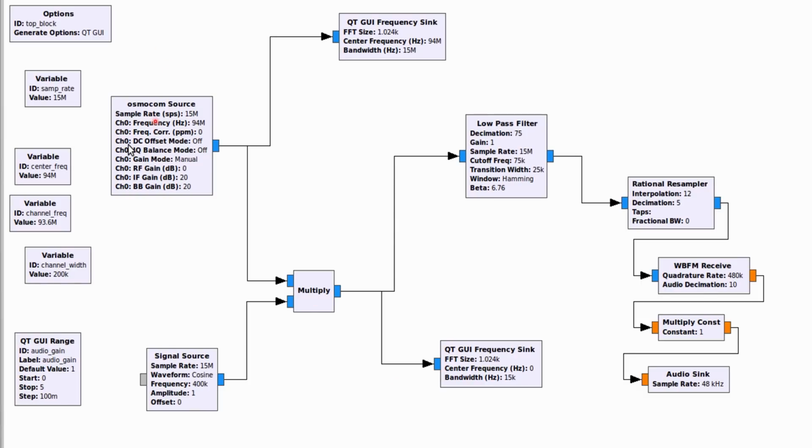It takes the IQ signal of the SDR receiver, demodulates it and sends it to the speaker. We easily can change the frequency to 145.525 MHz and the modulation from wideband FM to narrowband FM. Now we can listen to amateur radio. The same applies, of course, also for the transmitter. How cool is that? We can change the purpose of hardware solely by adapting the software.